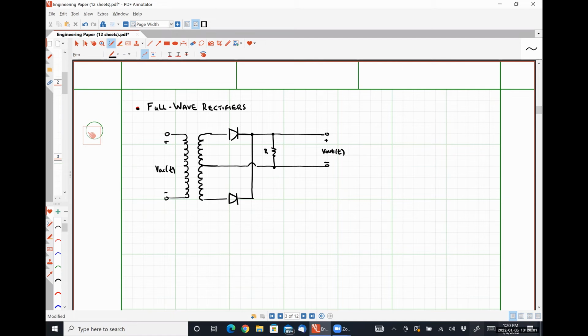So effectively, in our homes, our transformers convert probably something around 13.5 kilovolts down to 240 volts on the secondary, and then the secondary has a tap in the center so that the total voltage drop is 240, but we get two instances of 120 that are 180 degrees out of phase, okay? So in a similar process, we'd have Vn of t and negative Vn of t, where the center tap is effectively the common ground for the system.